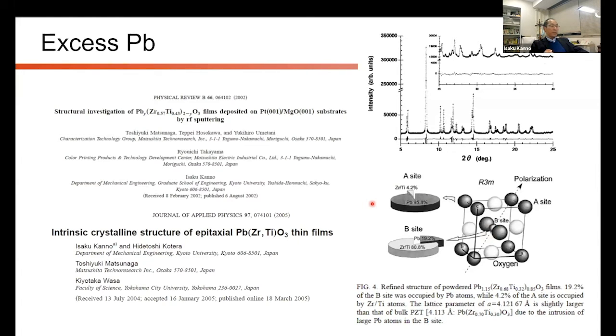Fujifilm produces highly niobium-doped PZT, and it's used for commercialized printer heads. I think it can be realized only by sputtering. The non-thermal equilibrium process of sputtering, such as the high speed bombardment of the sputtered species, is the reason for the different crystallization process of sputtered PZT thin films. But anyway, if we control the sputtering conditions, we can realize new piezoelectric thin films different from ceramics and sol-gel PZT thin films. That is a very interesting phenomenon for sputtered piezoelectric thin films.